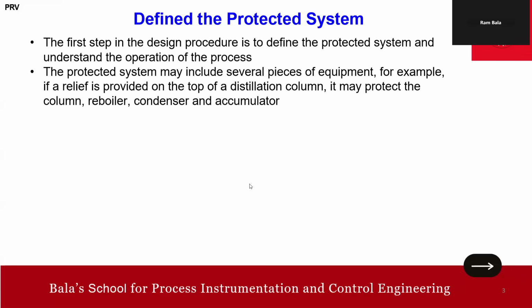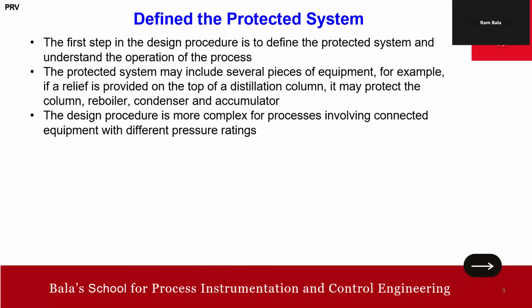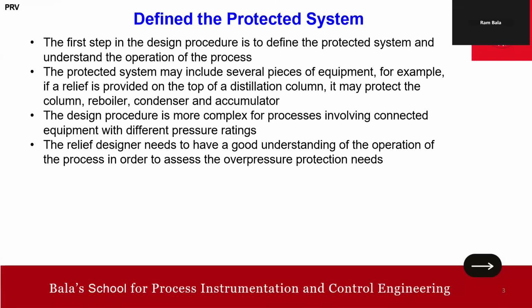This is how we need to define the protected system. The design procedure is more complex for processes involving connected equipment with different pressure ratings, so that also we need to watch out for. Take note: the relief designer needs to have a good understanding of the operation of the process. When we are given this assignment, we should have a good understanding of the process to assess the overpressure protection needs.